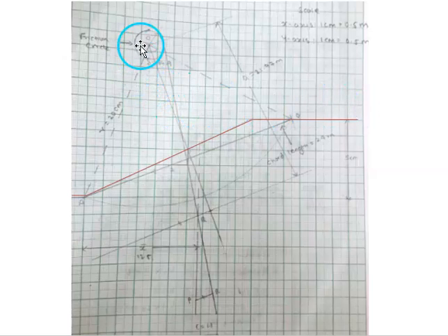After that, we have to draw the friction circle with radius kr sin phi. Then we have to mark the total weight with respect to the toe point, because the distance is given with respect to the toe point. By taking the distance, we can draw one vertical like this, representing the weight of the sliding soil mass.